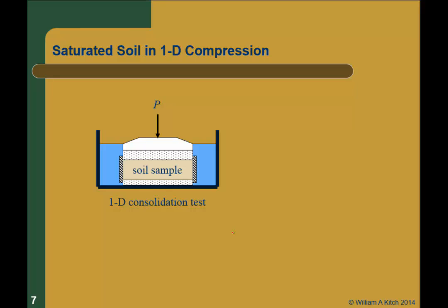What's the most important equation in all of soil mechanics, for those that ever took it from me? Terzaghi's concept of, it has to do with it being a 3-phase material. Right, and it's related to pore pressure. What stress is going to control how much this thing compresses? The effective stress, right? That's our state variable.